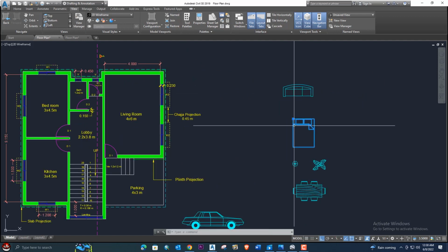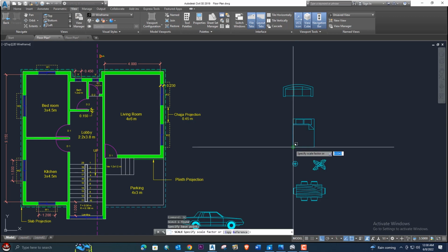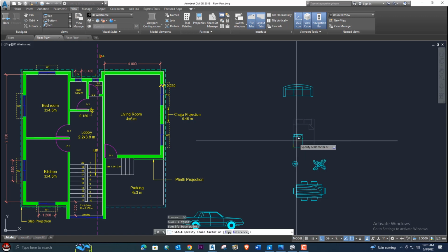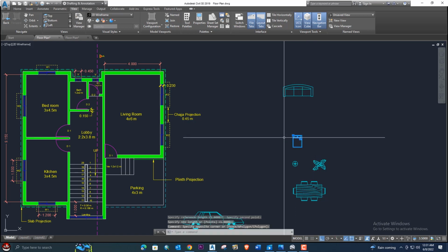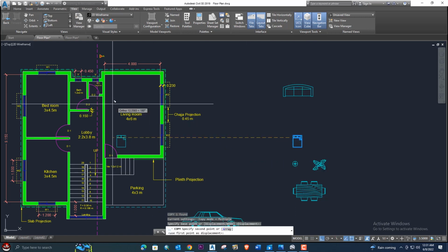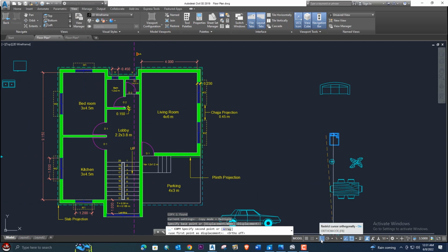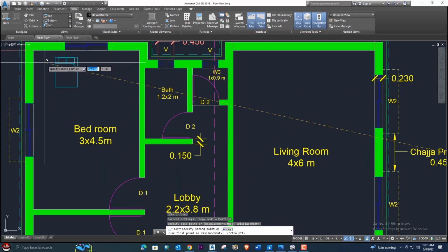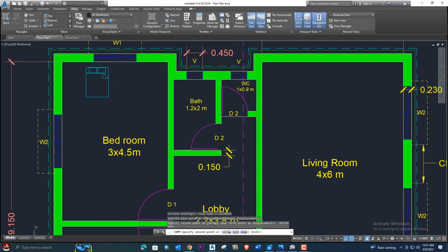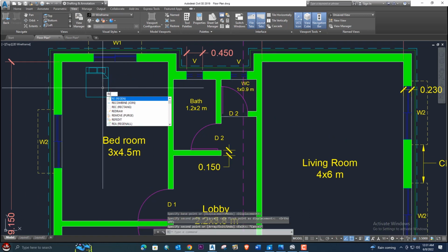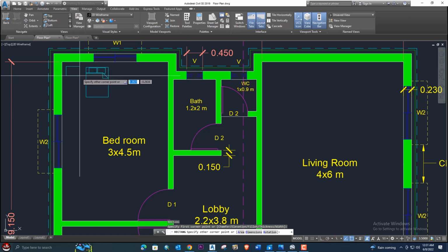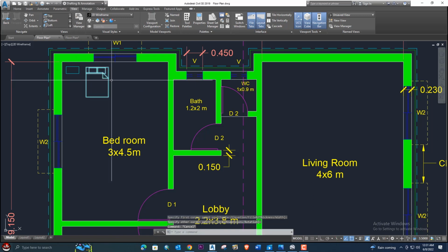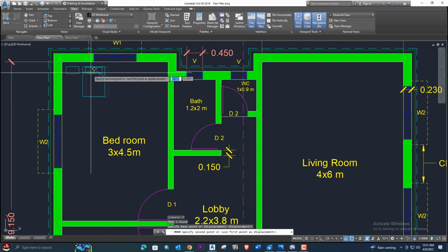First of all, we need to scale this, SC. From your keyboard, select and R for reference. With the reference, you can just select it, copy, and enter it to close the ortho mode. Once you close it, we need one table here, a side table. Use REC for rectangle, and you can just enter a table this way. Okay, and move this bed near to the table.